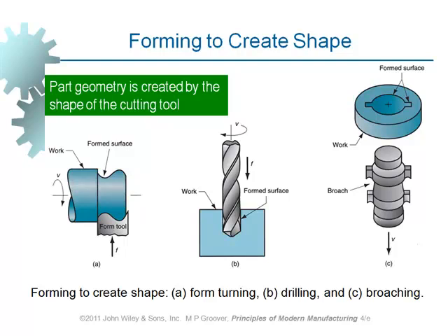In the broaching process, as you can see, a hole is initially made on the workpiece. And then the broach, which is the cutting tool, passes through the hole just like that, and it is pulled from one side to the other end. When the whole broach or the cutter passes through the hole, what is left on the hole is the shape and geometry of the broach.